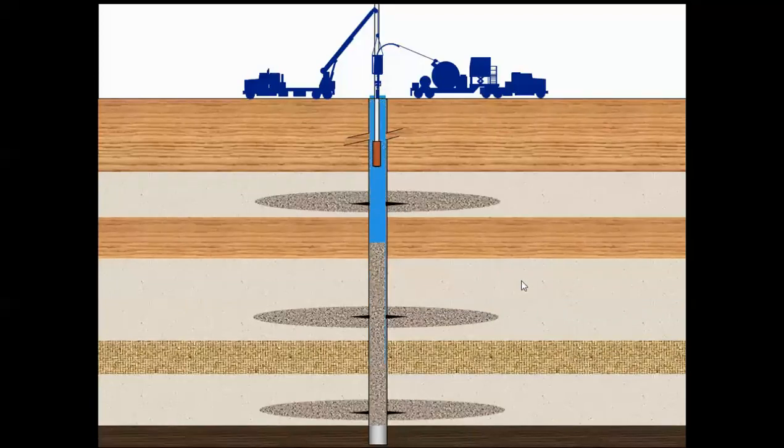Okay, so in this example, we have pumped 3 frac jobs in one well without causing too much time delay because we did not pull out the coil tubing unit, and we saved a lot of time. This is called multi-stage fracturing because there are multiple stages. So this is stage 1, this is stage 2, and this is stage 3. So there are different stages, right? After all the fracturing jobs have been completed, you can run the coil tubing again and clean out the remaining sand, and then your well is ready to produce.